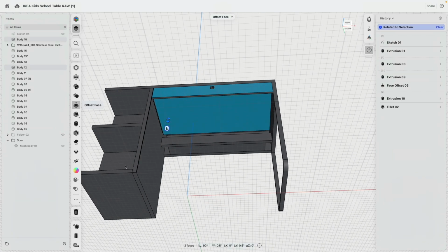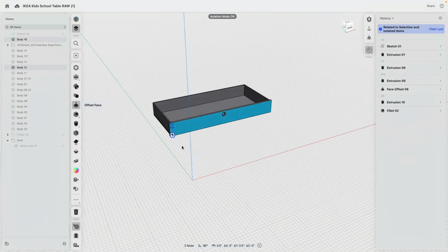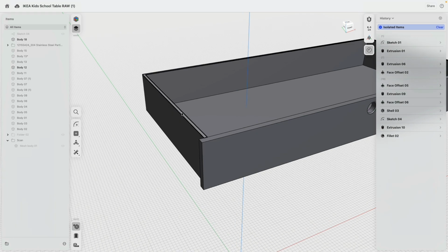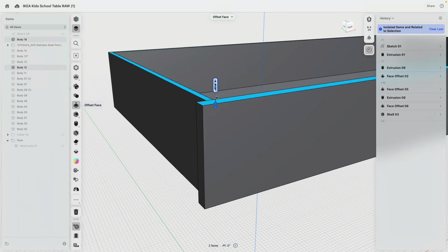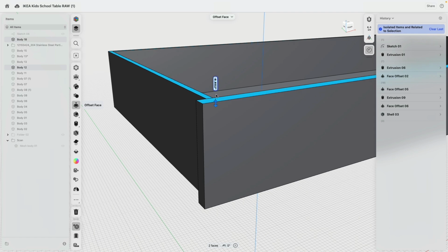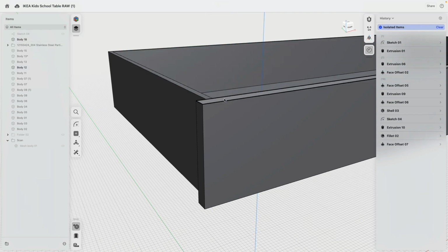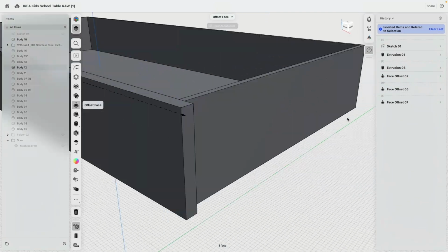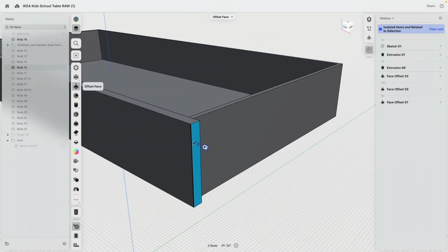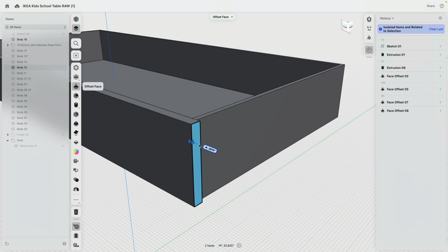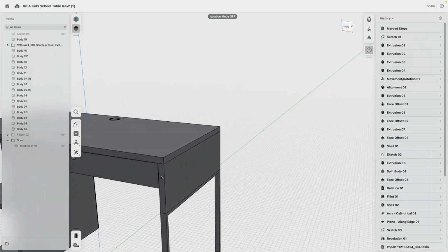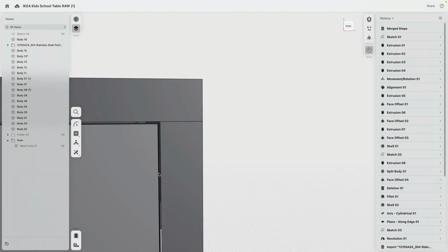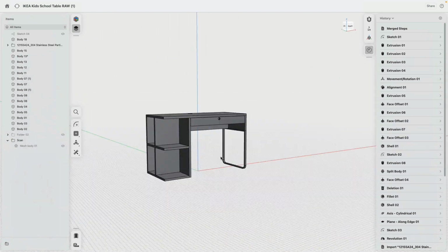Besides, one last thing, this drawer is going to really screech because it is way too tightly built. So here we need to add a little bit of an offset. 0.05 might be enough. And then here and there we bring this in 0.05. Very good. If we then show everything, there we see we added this gap. Perfect.